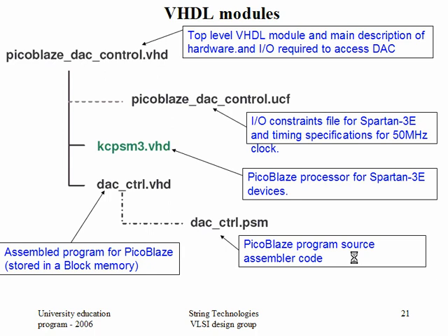See, I am showing a typical scenario. This is my top level VHDL module. This top level VHDL module has one component. This is actually the user constraint file. I think some of you can understand, for whom I discussed the user constraint file. Tomorrow you will come to know what user constraint file is. See, you are writing some code which is running inside the FPGA, but its inputs and outputs have to be brought to some pins of the FPGA, so they are called pin constraints.